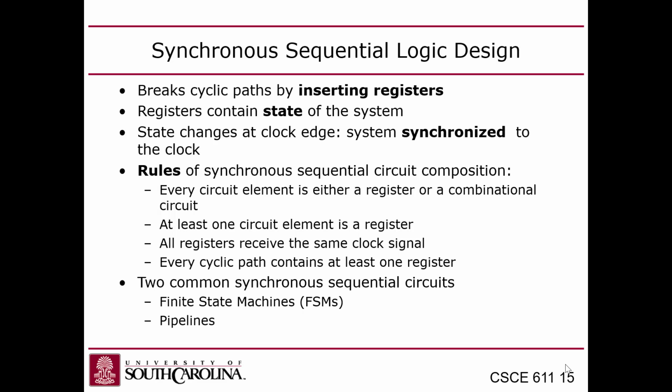And so a stack, we're going to create a hardware stack, right? Not software, because you can make a stack in software, or you can make one in hardware. So we're going to make a hardware stack, and we need a finite state machine to control it because we're going to have to sequence operations to that stack. Because in an RPN calculator, the idea is that you push values onto the stack, and then you do an operation. And when you execute an operation, you have to pop two values off the stack, generally, do the operation on those values, and then you push the result back on the stack.